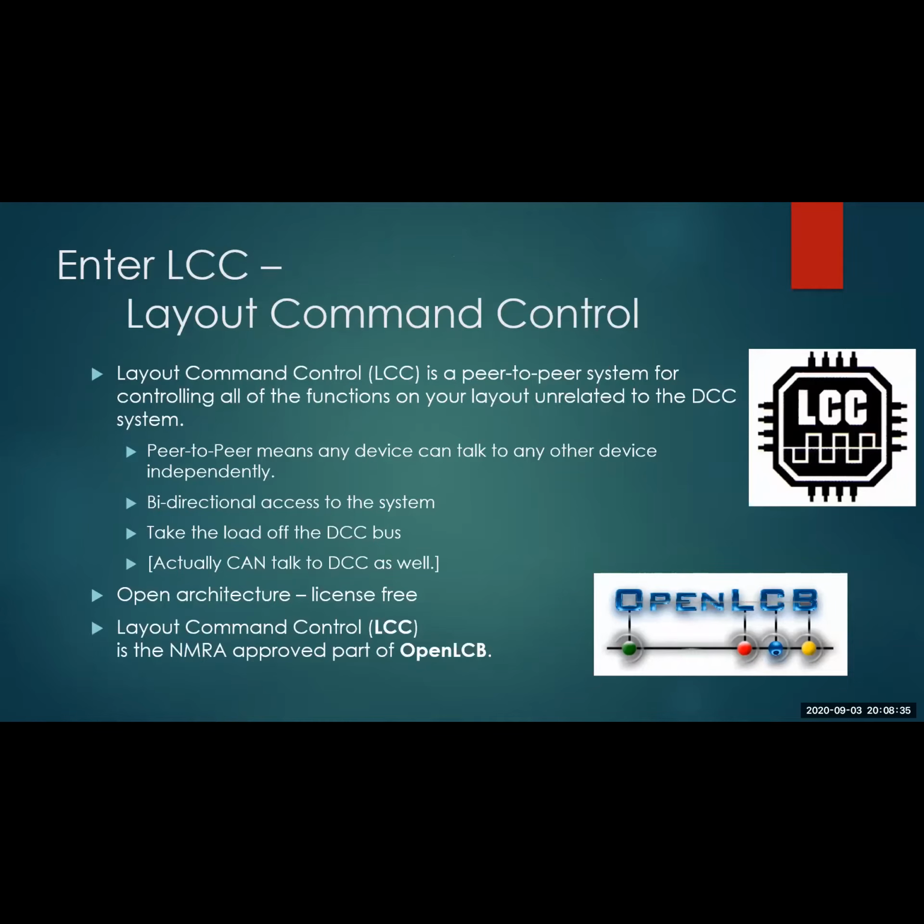As I mentioned, it takes the load off the DCC bus. And it actually can talk to the DCC bus. It talks through JMRI. LCC goes through JMRI just like many other things. So you can actually talk to the DCC bus if your DCC is tied into JMRI. And I just saw, by the way, RR Circuits came out with a Digitrax Loconet to LCC buffer. So I understand that just came out, so you can have a direct link between LCC and Loconet now.